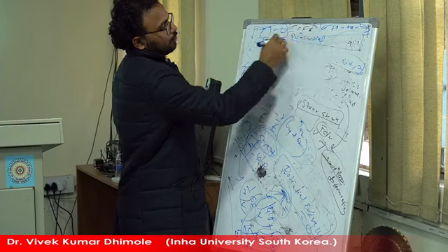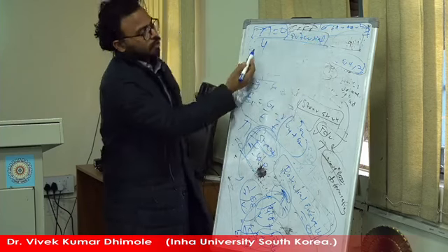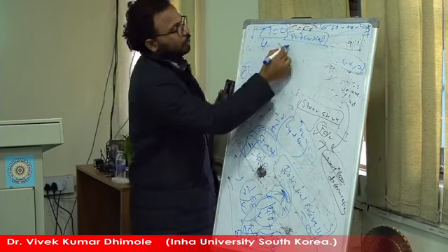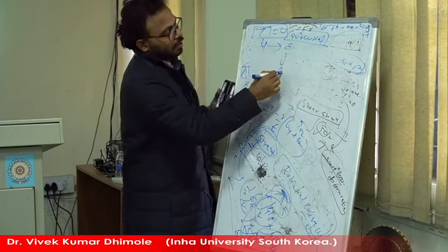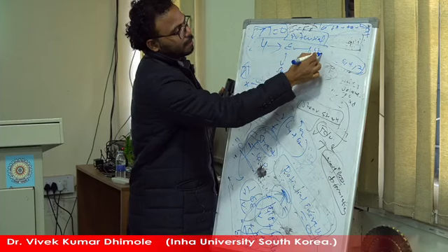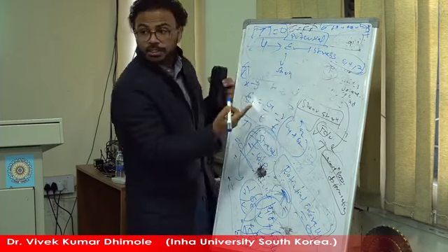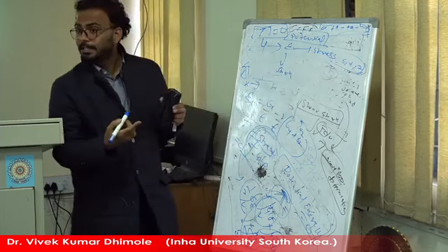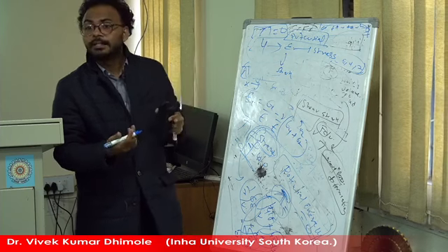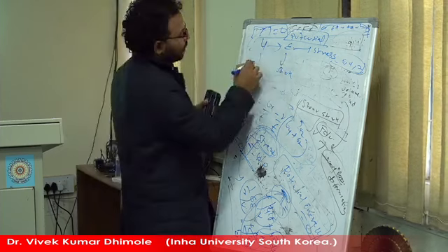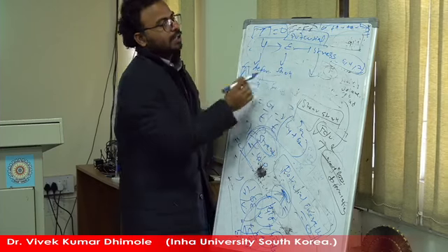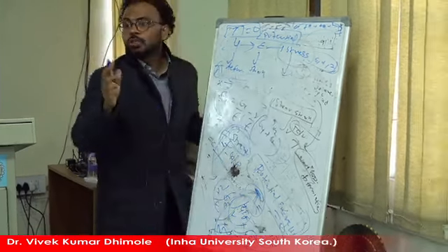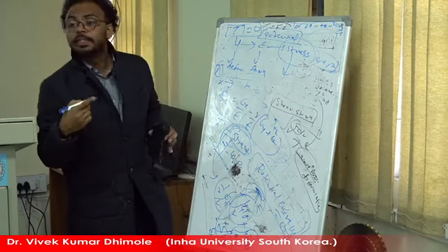So when you work with finite elements, you get the deformation first. Then from u, you get epsilon, the strain. Then from the strain, you get the stress. And they are correlated to each other, right? We checked it by Hooke's law, the deformation law. So you get the deformation, strain, and stress. Finally, you get the stress result, and those are needed for design purposes.